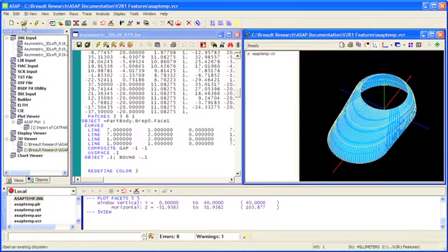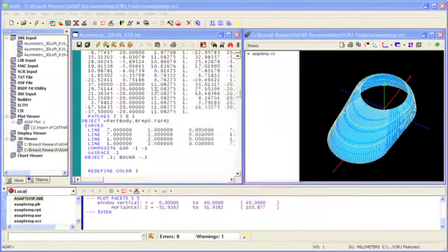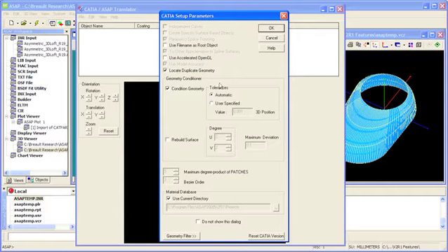Now, let's repeat the translation process using the rebuild surface option instead. And this option actually lets us choose the order of the surfaces that we want to create in both our U and V parametric space directions. And again, we can define a maximum tolerance in system units for the rebuilt surface, and the Bézier patches will be constructed to the accuracy that we want.